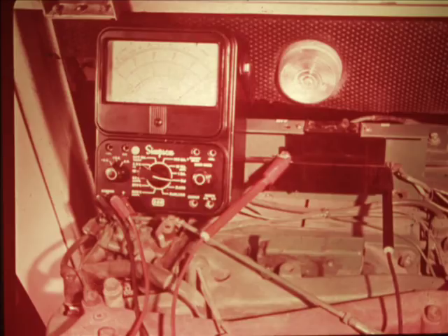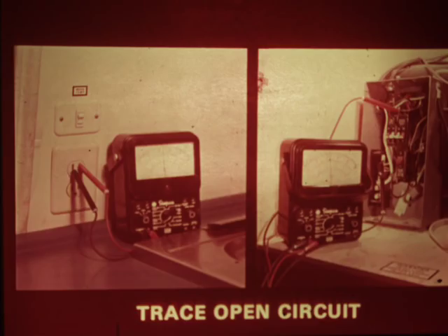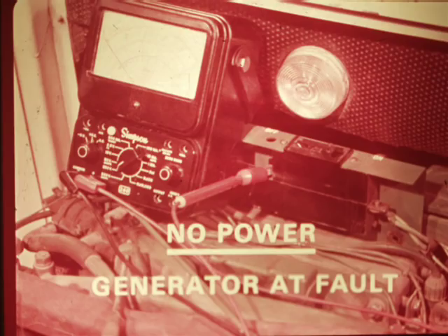The first thing you do to locate the problem is make sure the breaker isn't faulty. So with the breaker on and generator off, check across the breaker with an ohmmeter or self-powered test light. If there is continuity at the breaker, then to locate the open or short, trace back through the circuit in question and to the circuit breakers in the electrical compartment inside the motorhome. If, when you test the generator side of the circuit breaker with the breaker open, there is no power, you will know that the trouble is in the generator, and the generator needs to be tested.